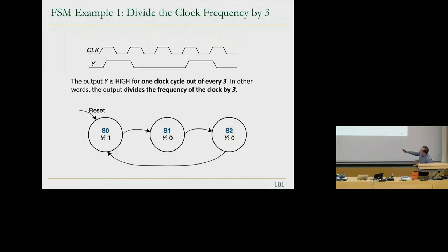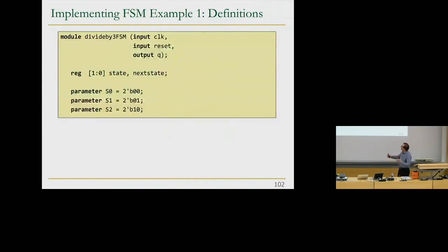It's 1 only in this case, the first state. The next state happens, it transitions to 0. It stays in 0 for 1 clock cycle. And the next state happens, it transitions to 0 again. It's still 0. And when you go to the next state, it goes back up to 1. Well, this is a simple clock divider circuit. It basically reduces your frequency.